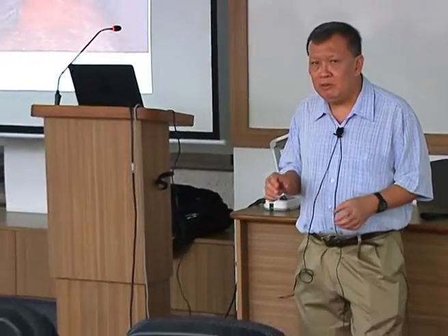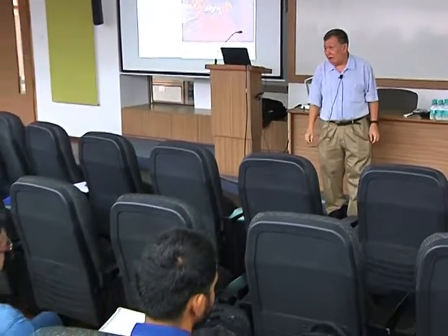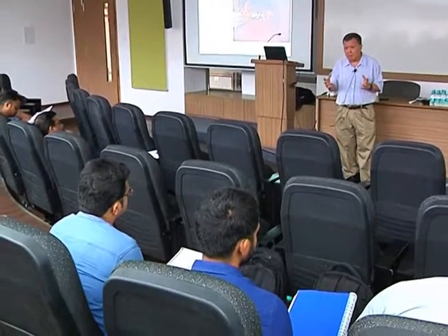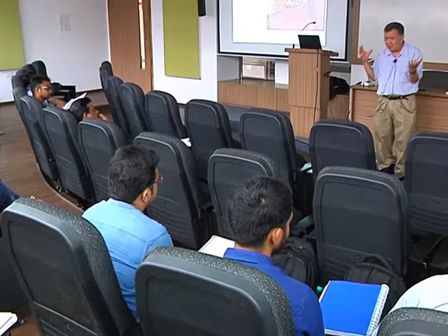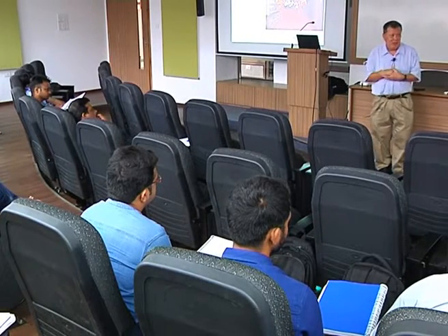Now, the geotechnical consultant is an American tunneling guy called Kirk Seidler, from New York, I think. In fact, we still correspond. Sometimes he still sends me New Year cards and things like that. And he was doing 2D analysis. The problem with 2D analysis is that you can never model the longitudinal beam action of the forepole. You can only model a tunnel section. The forepole is as good as being useless. You know what I mean? So that's why you need a 3D analysis.